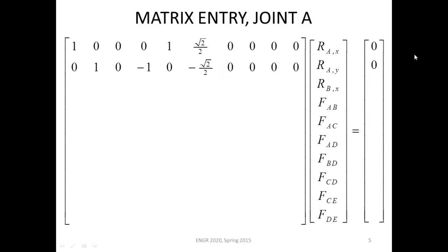The right hand side is 0 unless I have a number that I can move to the right hand side, and that would be listed in this column here. So all the unknowns are on the left hand side, all the knowns are on the right hand side. In these two equations, they were all unknowns. Nothing was known. As part of this method, we don't start analyzing equations until we have written the entire matrix. So the only knowns will be the external forces acting on the truss, which are given as loads, not supports. Supports are what we are determining as part of this method.